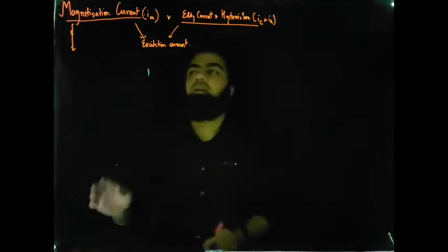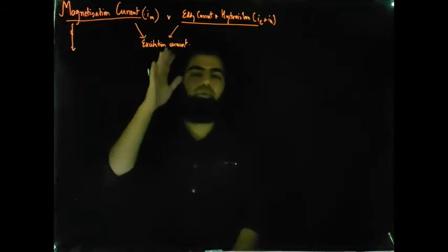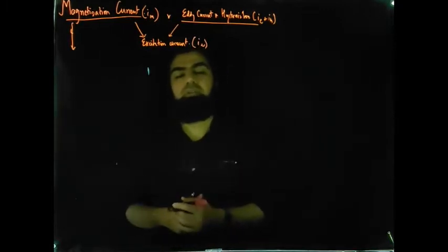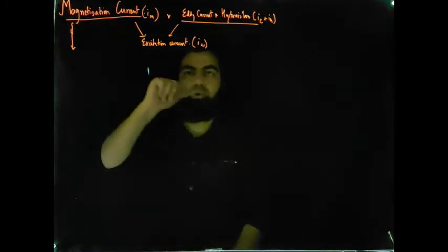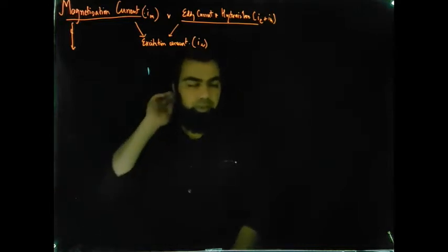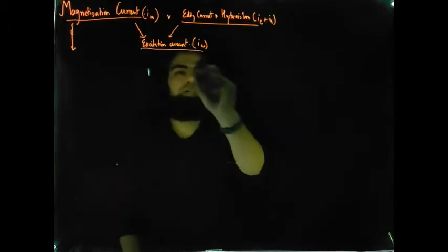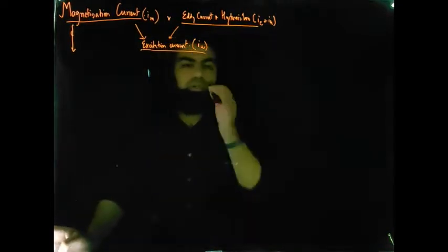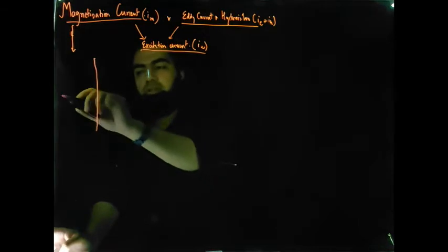We want to actually see the profile of both the IM as well as the core loss current, and therefore we want to see the total profile of this excitation current IE. So once we know how these three currents look as compared to the primary voltage that's applied to the transformer, we'll be able to model them using certain parameters like resistance, inductance, etc. Right? So the magnetization current is responsible for generation of flux in the transformer. So we know how the magnetization curve is.